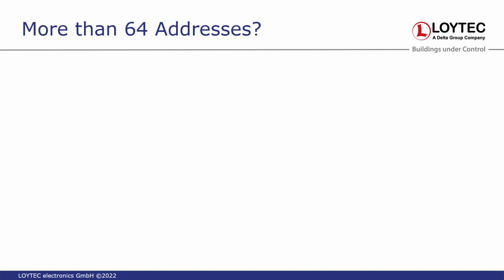I understand. Or is overloaded. I'm mainly in the field, and I can tell you that a lot of the time the bus will be overloaded by the contractor. They will try to put more fittings onto the DALI line than is recommended. Normally, what some other manufacturers do is pull in the short addresses, and once we get up to 63 or 64, it will stop and inform you that you have too many devices on the network.